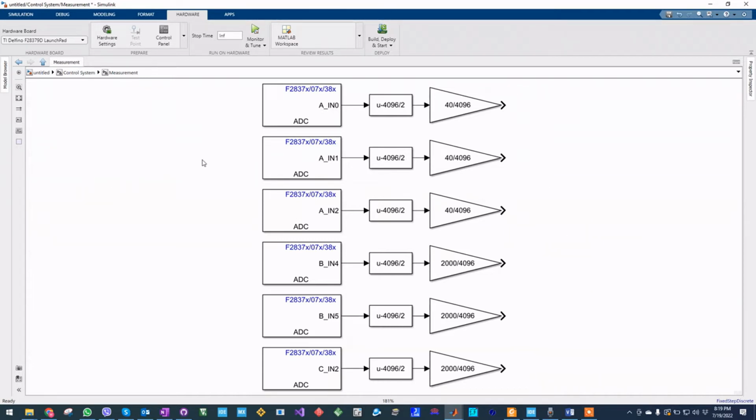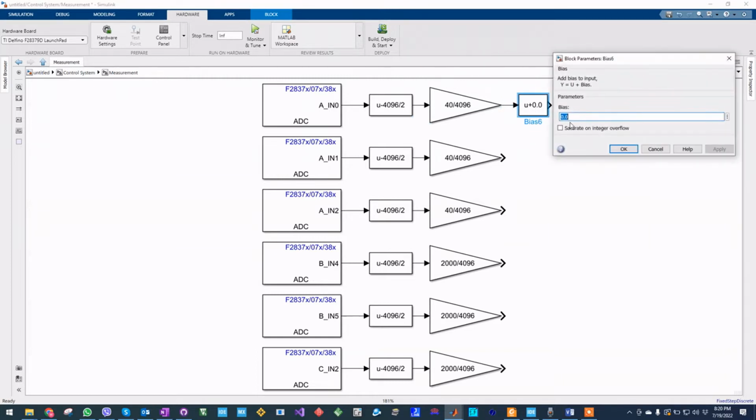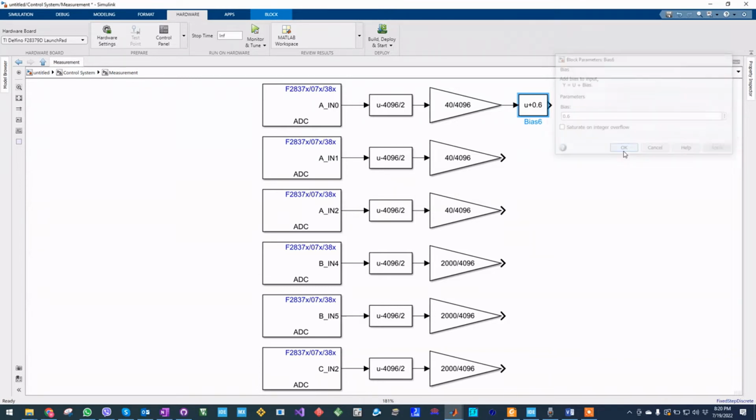As the ADCs are generally operating on the basis of op-amps, we have some bias on each analog measurement. So we have assessed this bias, and we will subtract this bias from each channel. These biases are already pre-computed, so you will have to insert these as they are in each block. For each channel it will be a little different.